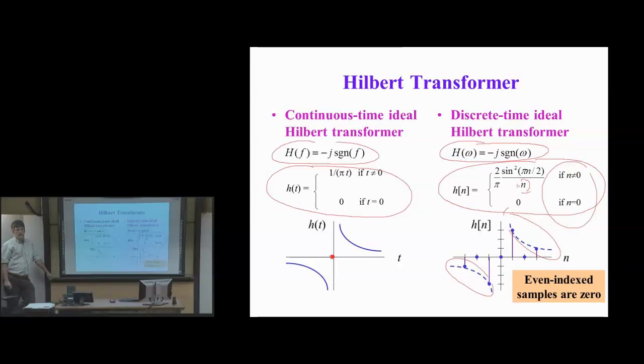Window it, and then what? Well, that's already sampled, the one on the right. It's not downsampled yet, but let's just make this something that we can put into an FIR filter block. We can throw away the zeros at a later time, because this happens with interpolating filters and so forth anyway. But what we do with the raised cosine, or the sinc that was two-sided, what did we do to make it implementable as a pulse shaping filter?